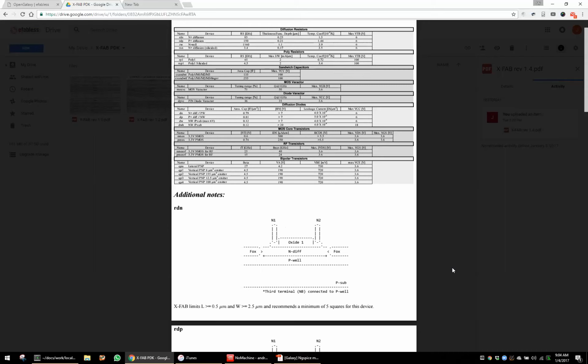You can always do this: once you define a bus, you can say V of square bracket 3, V of square bracket 2, and vary the voltage of individual lines in this bus. Okay, thank you very much. By the way, when errors appear on my screen, I take a screenshot. I use Linux here. I take a screenshot and send the images to you. Then you can see exactly what I see.